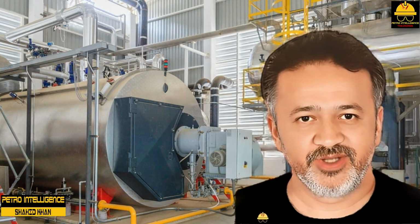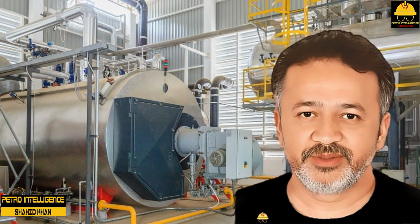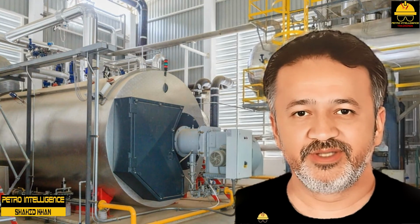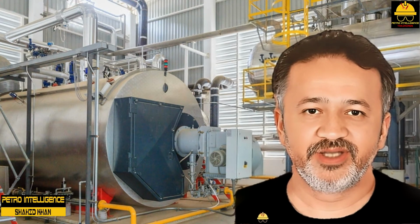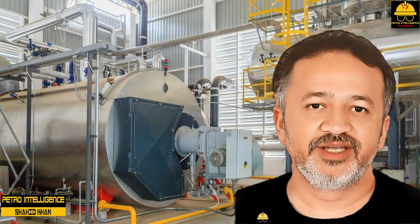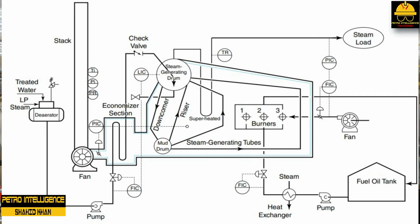Condensate can cause many serious problems as it flows with the steam. Slugs of water can damage equipment and lead to a condition known as water hammer. Devices known as steam traps are used to remove condensate. Steam traps are grouped into two categories, mechanical and thermostatic. Mechanical steam traps include inverted buckets and floats. Thermostatic traps include bellows-type traps. A steam system that includes a steam trap is shown in the picture. Inverted bucket steam trap.